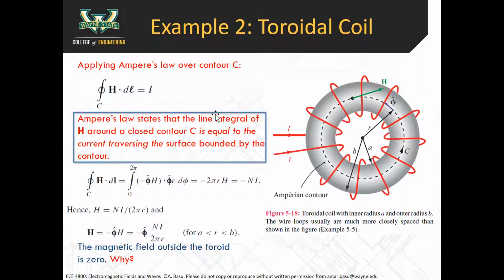If you imagine on this part of the toroid, where I'm pointing right now, the current is going inside like this, so it's going to generate a magnetic field around it. Thumb is going into the screen, and the magnetic field that's generated in this segment is going around like this, clockwise. And the same thing is happening on this side. So when you add up the contributions of all of those coils in the wire, you end up getting a magnetic field that's going through the coil. Okay, and this is the same thing as a regular solenoid.